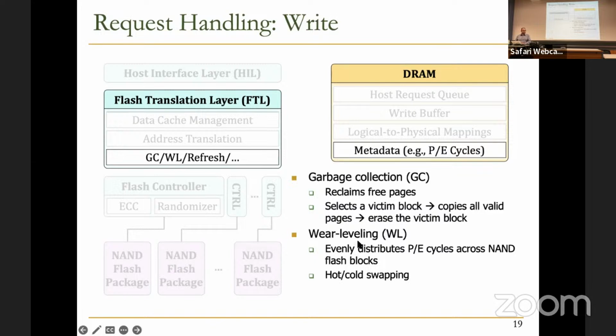Wear leveling is also another important operation. As we discussed, these memories all have an endurance problem. And if you keep writing to the same location, your device will wear out quickly. So wear leveling is an important task to evenly distribute program erase cycles across NAND flash blocks. So that's why we need wear leveling. And there can be a lot of implementations for wear leveling, but